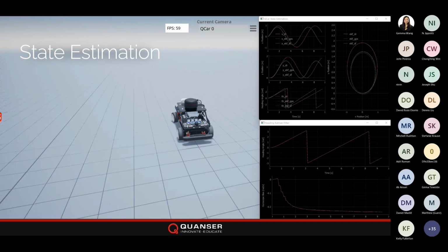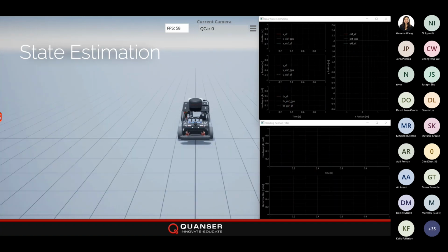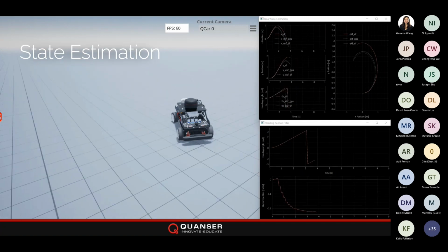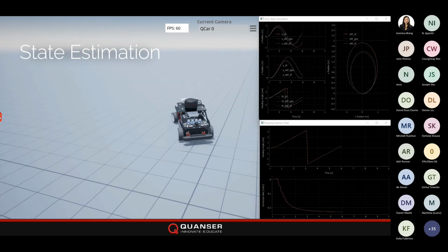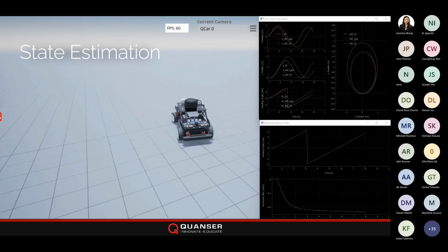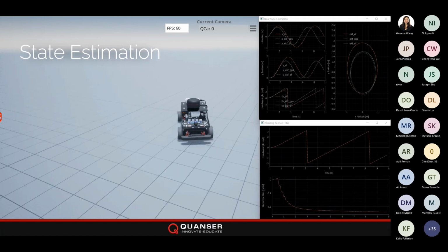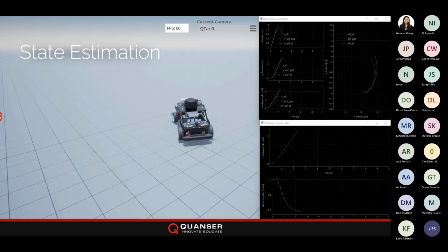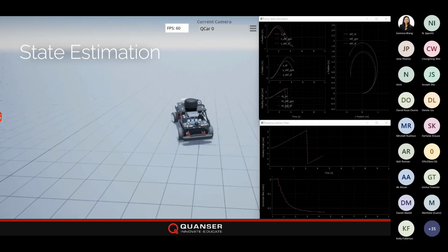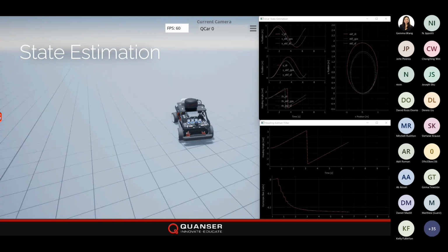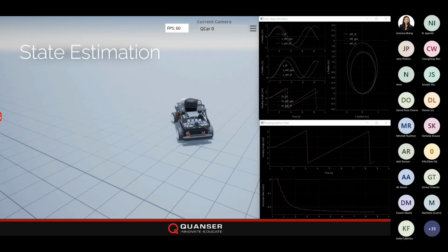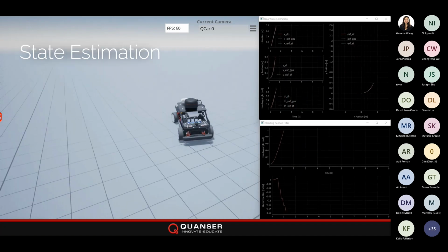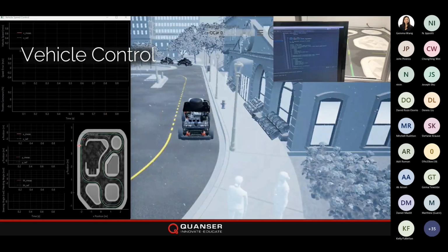Oh yeah, the scope on the bottom there is showing you that for the more complicated filter, we also estimate the gyroscope bias, which is another thing we talk about: some of the issues with inertial measurement sensors, and that inevitably when you integrate, errors accumulate, and they have other properties like constant biases. To get a better estimate, you can estimate what those biases are and then remove them. Okay, so we have a state estimate.